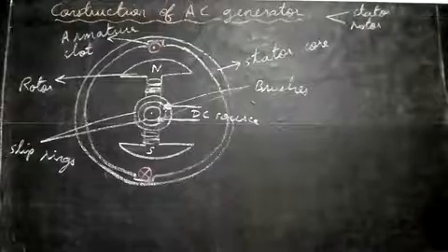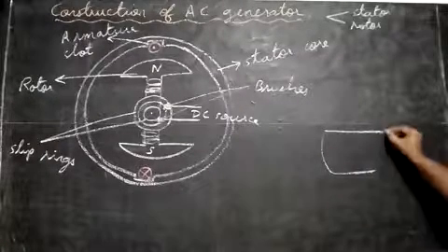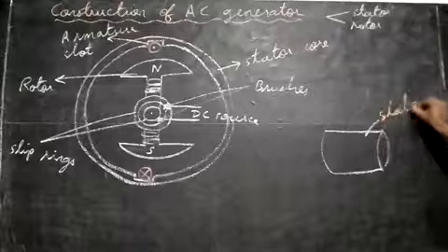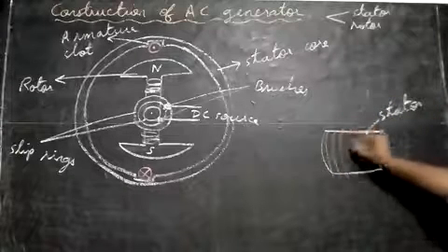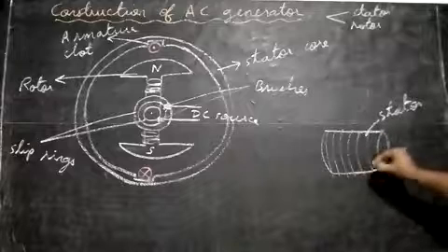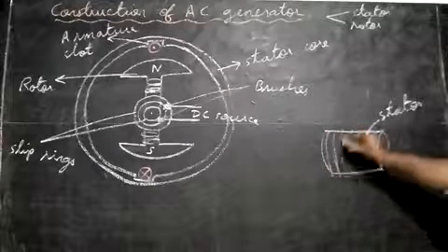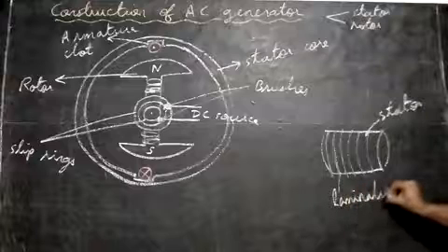The stator core is actually like a cylinder only. Seen from the side, from outside, it's like a cylinder. But it has many laminations, many circles. It's made of many circular parts, and it is laminated also. There is lamination between these parts. We have lamination to reduce the eddy currents.